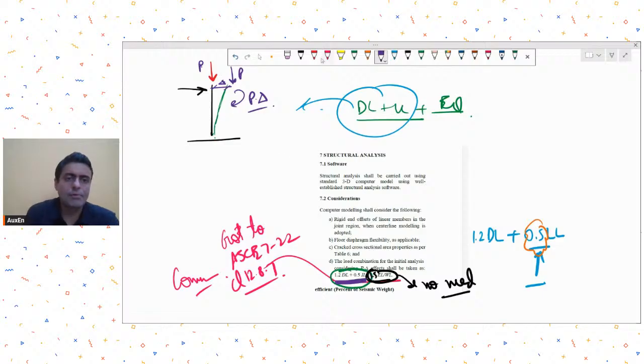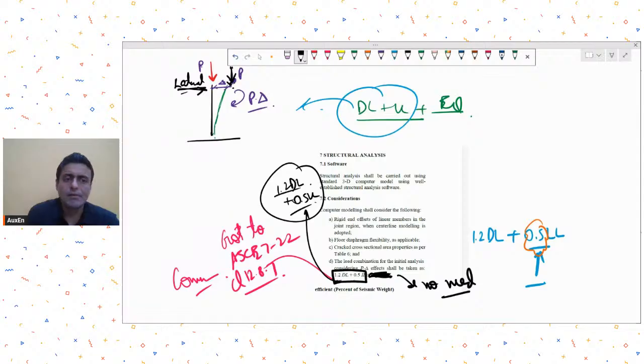So this gravity component we need to apply on our member, which will result in additional moment when there is a lateral deformation due to some lateral load. Understood? So this should not have been there. What they should have written is that you only take this in the preset P delta option, only this, and then automatically the effect of this P acting will be seen in all the members for any lateral load, and then it will be included in all the load combinations also.